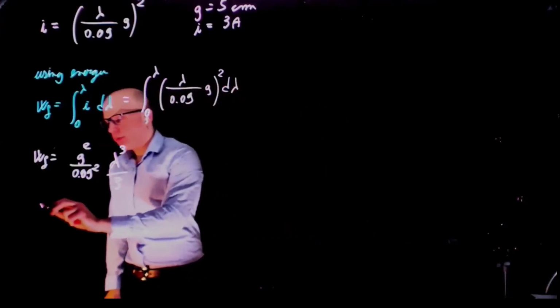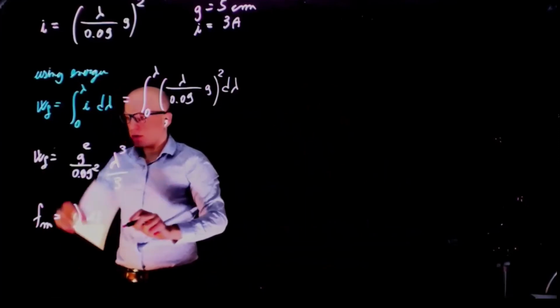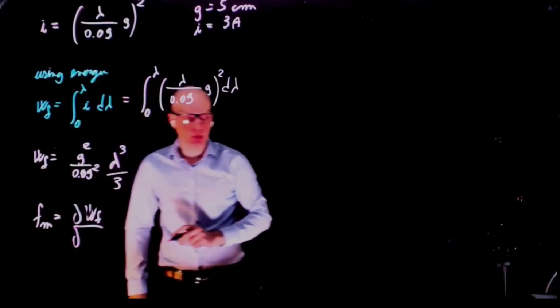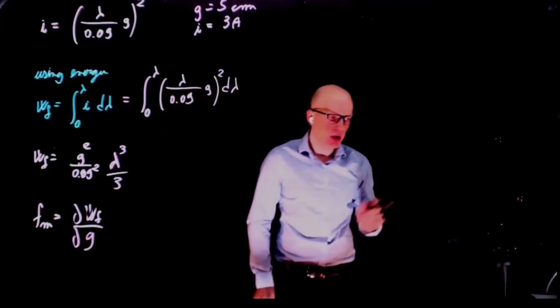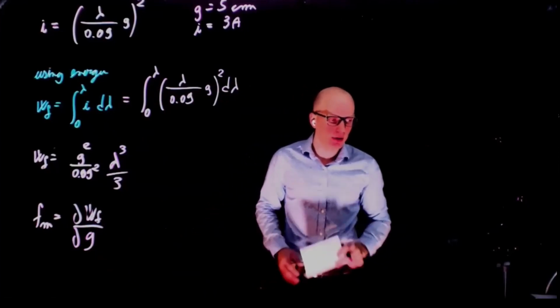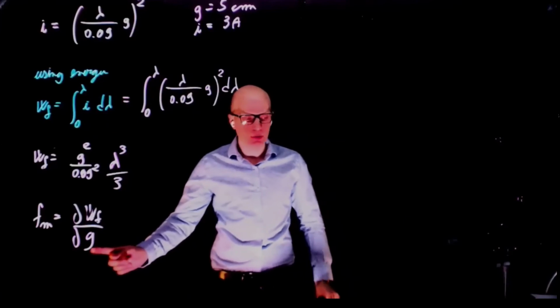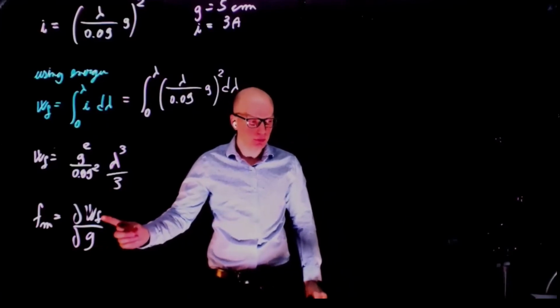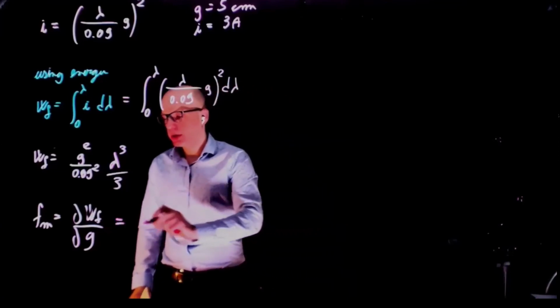What is the mechanical force? The mechanical force is the derivative of the field energy with respect to whatever is moving. What is moving here is the air gap. The air gap is decreasing. That's what is creating the change in the magnetic field, and that is what creates mechanical force. So dWf/dg.